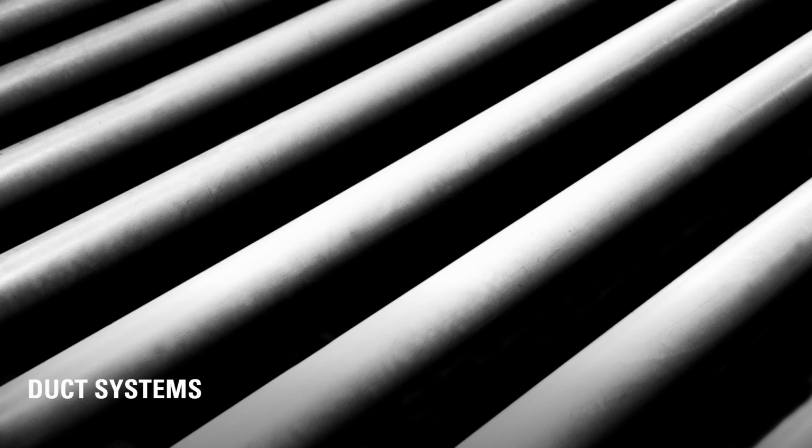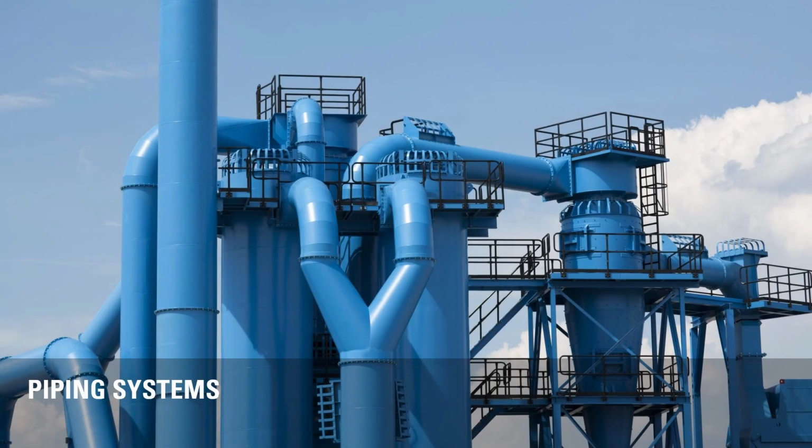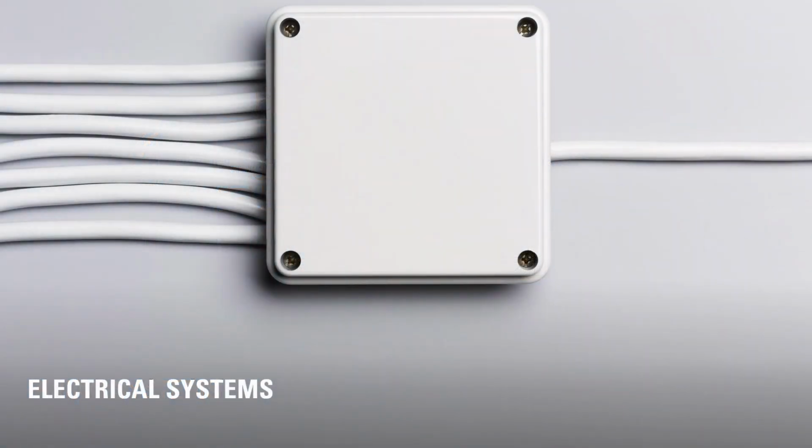Duct systems. Duct systems meet airflow requirements and heating or cooling loads. Systems are created by placing air terminals and mechanical equipment, then using Revit's automatic system creation tools to route ducts. Piping systems. Piping systems are logical structures that enable Revit to calculate pressure, flow, and sizing. They are created by connecting piping to mechanical equipment, establishing supply and return systems. Layout tools help you explore routing alternatives.